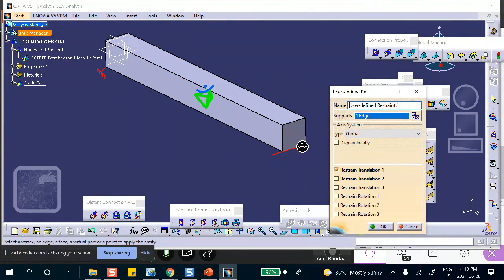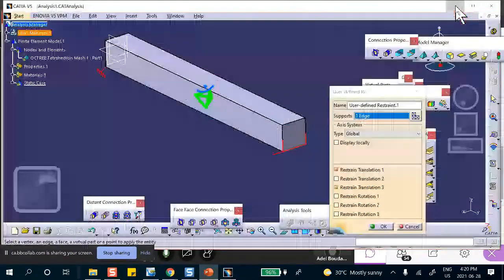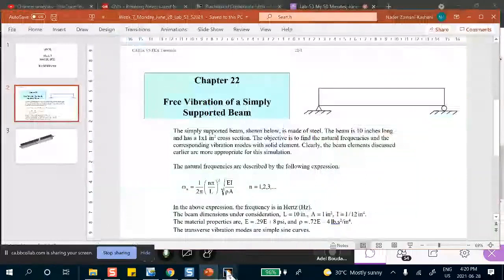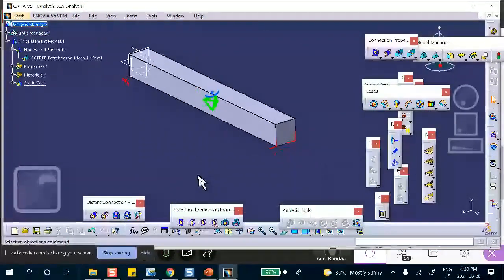When I clamp it, basically I'm saying that these 2 points cannot move at all with respect to each other, okay? Now, here we said that, okay, we're not going to let it move up and down. That's Z. And I'm not going to let it move in the direction X, okay? But I'll let it go in the direction Y so that it can actually do this if it wants to. It won't do it for linear analysis, but in real life, that's different. Good, good. Okay. Now, save everything.